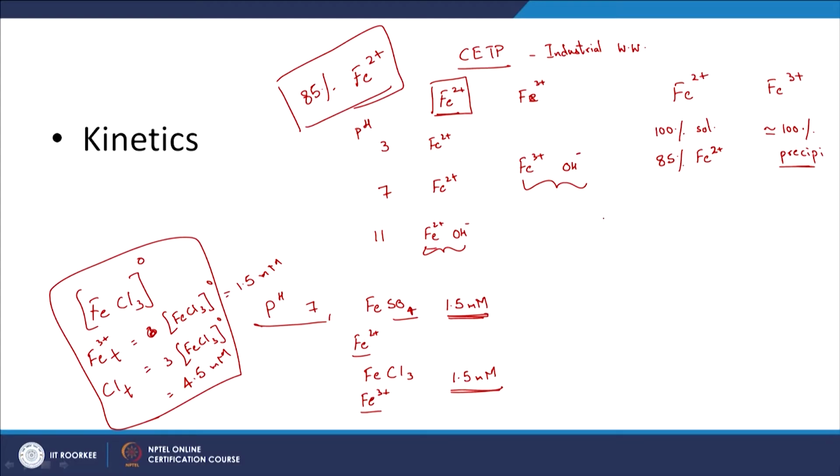In general, how does coagulation occur now? Coagulation, there are different mechanisms. The first mechanism is charge neutralization, let us say. Again that is self-explanatory I guess. Charge neutralization, as in your suspended particles or colloids, people presume that they have a negative charge, and that is a good enough presumption actually, and even in industrial wastewaters people presume that. Again, I am saying people presume that, but it can vary. There are sometimes cases when you have colloids with a net positive charge rather than a net negative charge. Anyway, charge neutralization as in you add the counter charge.